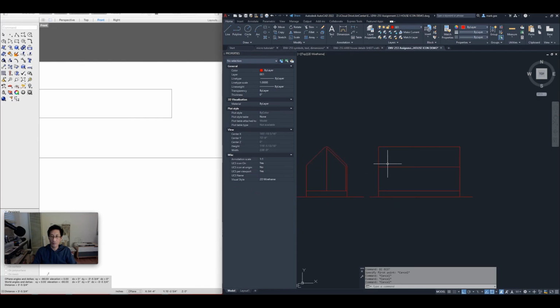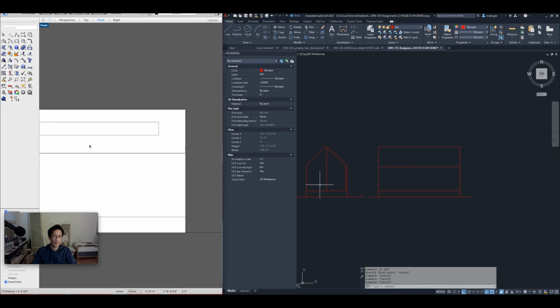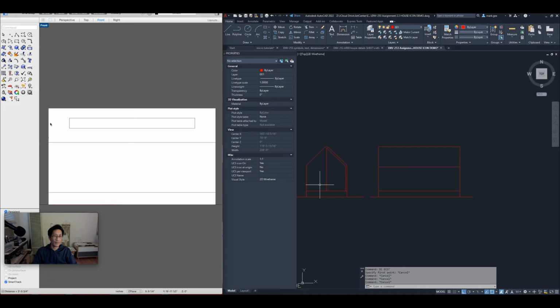What I'll do here is I will simply draw a rectangle, since we know that that's 5 feet and that's 5 feet, and the whole thing we've already drawn at 40 feet. We know that the length of this is 30 feet then, and we measured this at 30 inches, so it's 30 inches by 30 feet. So I'll just go ahead and draw a rectangle like that, and then I'll move it into place.